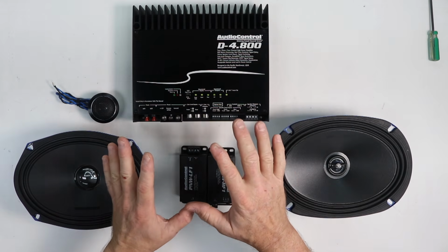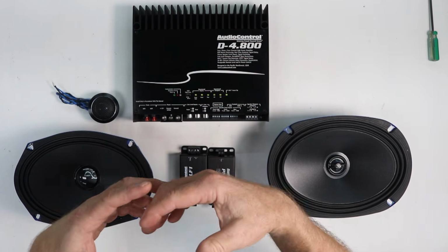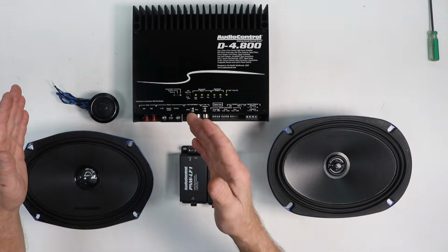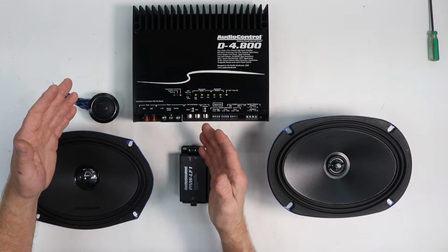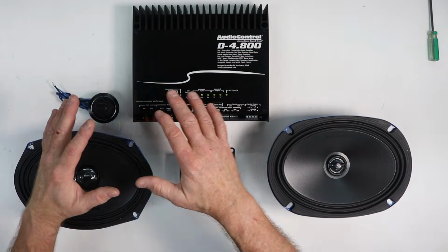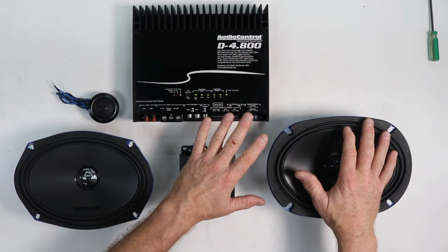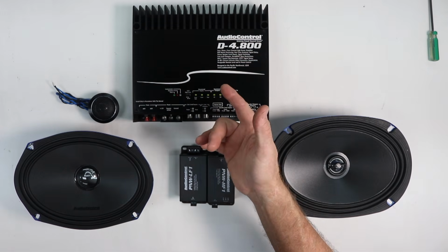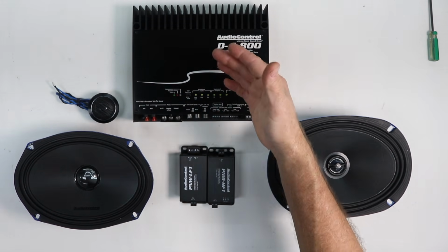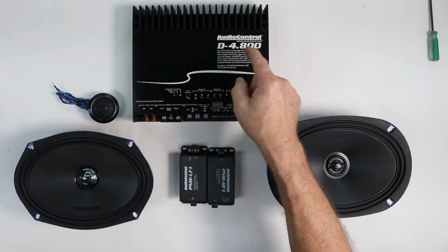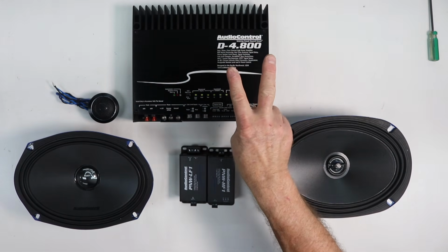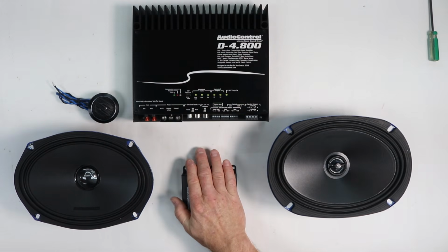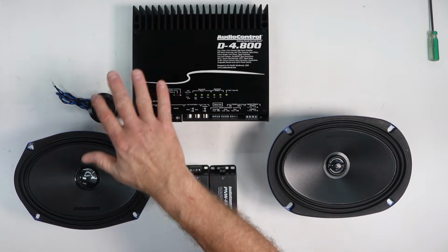car. So looking at all of this that we now have journeyed through, we figured out that even though we have a DSP amplifier, in some cases we might have to go passive on those component sets so that we can amplify the speakers we've chosen. How do I avoid it? That's always the thing. Know how many channels you're going to need to accomplish your goals. In this case, we could have jumped up to the D6-1200, and that would have given us 2 extra channels so that we could have powered these on their own, thus removing these and going full active with this scenario.